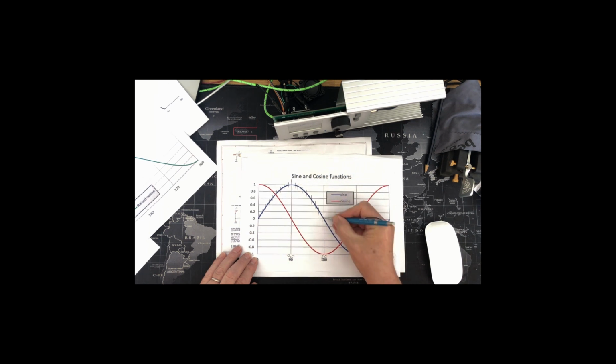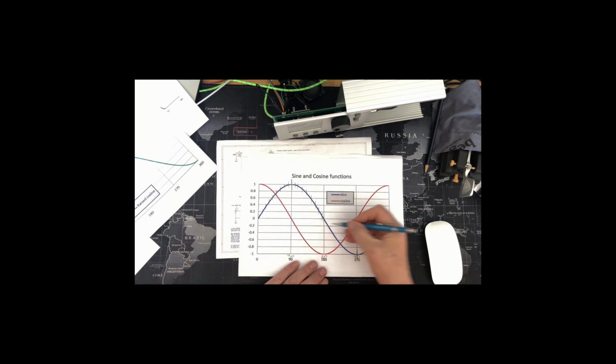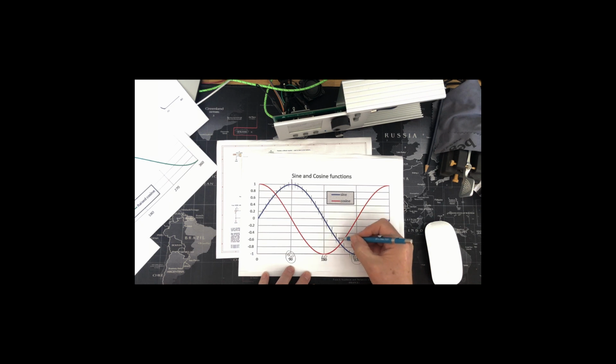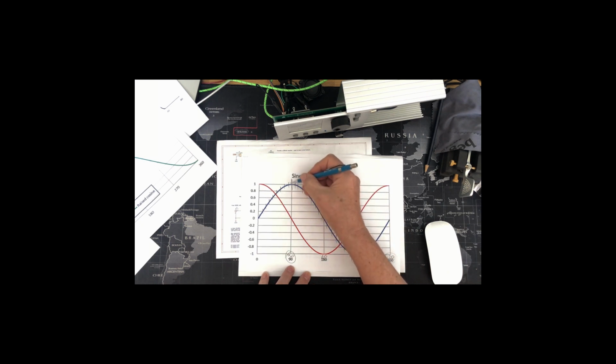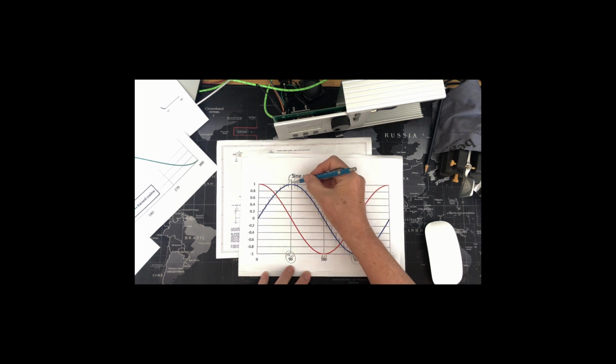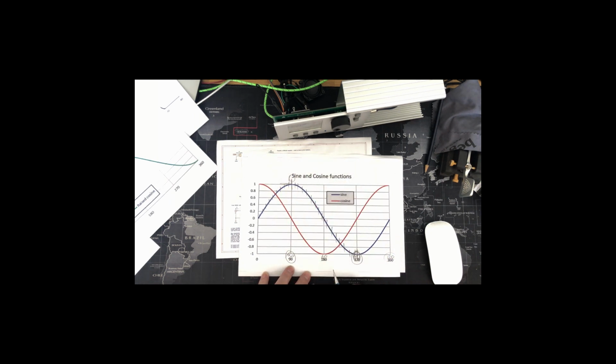section of code. And the bins that I'm interested in are between 90 and 30. So when I come to transmit, I'll load bin 90 into the DAC and decrement each step until I get to bin 30, and that will be the maximum output from the DAC.